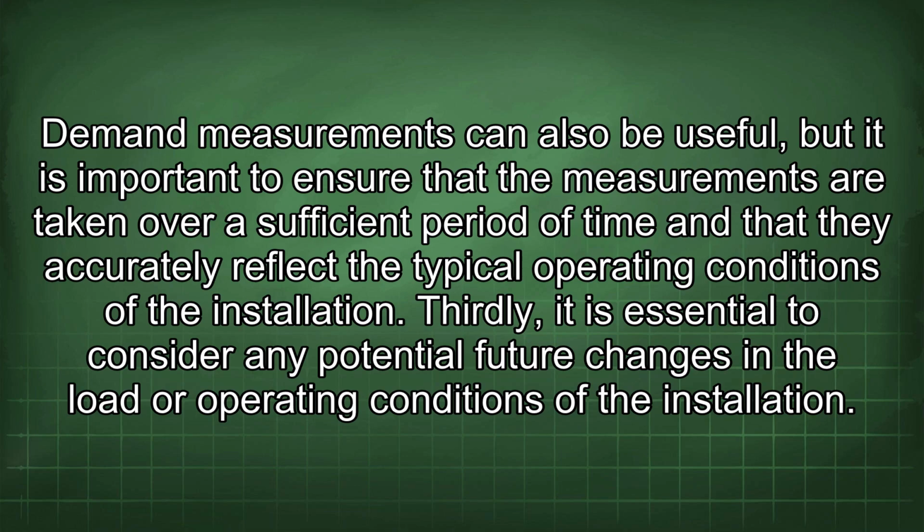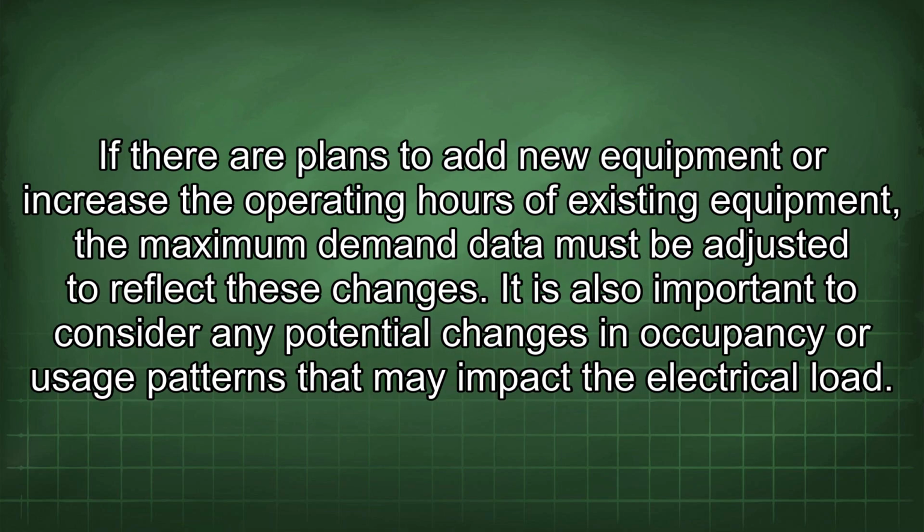Thirdly, it is essential to consider any potential future changes in the load or operating conditions of the installation. If there are plans to add new equipment or increase the operating hours of existing equipment, the maximum demand data must be adjusted to reflect these changes. It is also important to consider any potential changes in occupancy or usage patterns that may impact the electrical load.